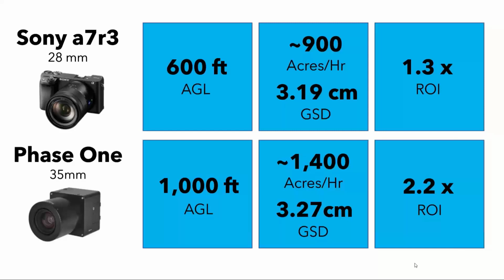I think it's pretty neat if you go on to the FAA Part 107 waivers issued. You can click that link. It's a link to the FAA's website, and you're able to filter and look at all the different approved entities for all these different waiver classes. What we're talking about here in high altitude, in that search bar, type 107.51B in parentheses, and you're able to look at all the entities that have garnered this permission before.